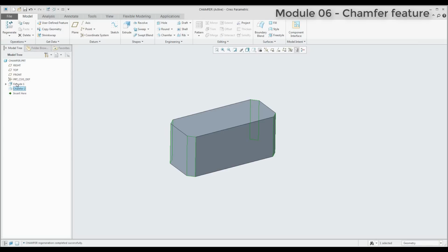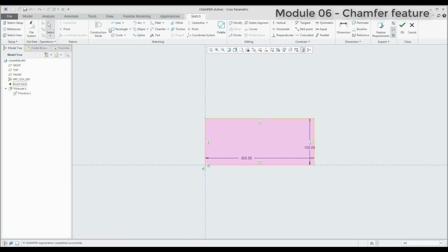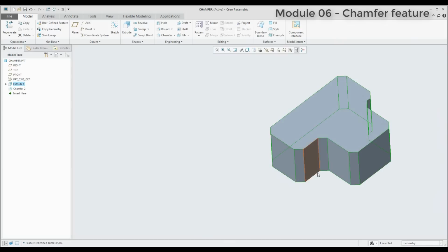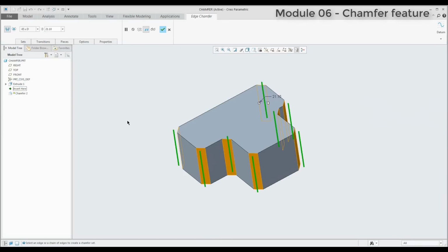While I would like to use the intent edges, if I change the shape of the extrude feature, and for example add another shape here, so you can see that I can add something, and if I finish, the system automatically creates the chamfer on the defined intent edges. Yeah, so if I select the definition, you can see the system will automatically create the chamfer for me correctly.